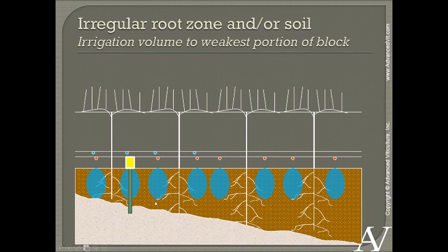Even better than that would be to do a full soil exploration, but not everybody has the funds right away to do that. Often we'll use the aerial imagery to site where to put that soil probe.